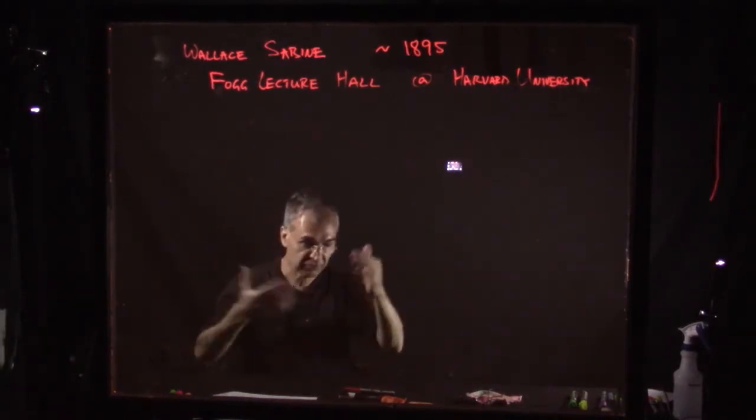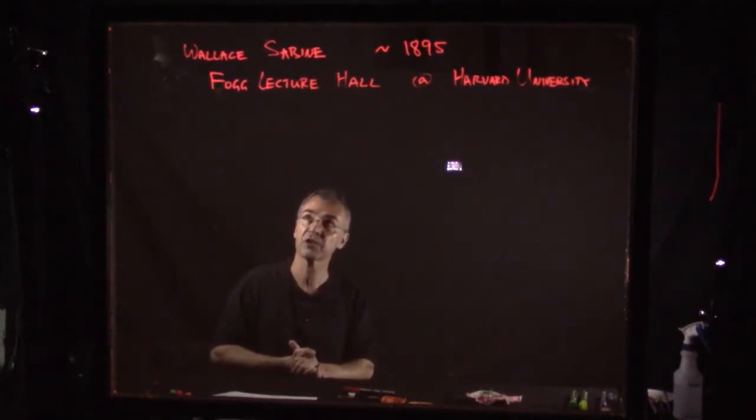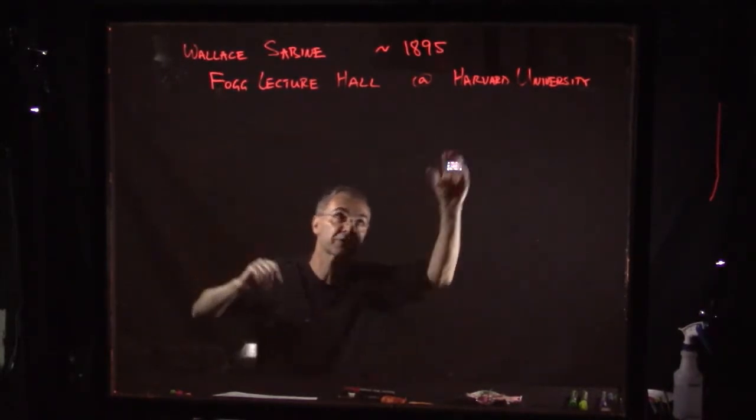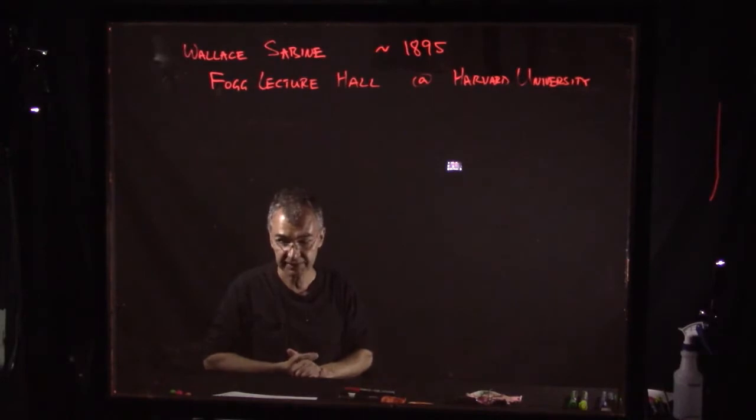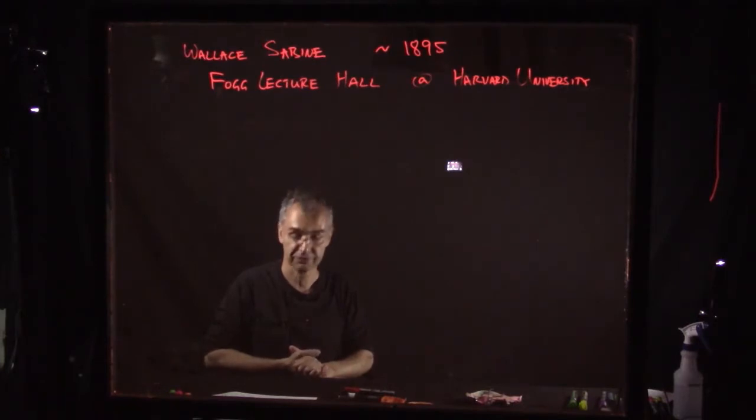And now some locations turn out to be more effective than others. It often turns out that the corners are the place to start because the corners are one of the more effective places to absorb the sound. But in any case, he varied the number of these seat cushions that he put along the walls of the lecture hall, and made careful measurements of what the effect was of varying the fraction of the surface area of the lecture hall that was covered in seat cushions.